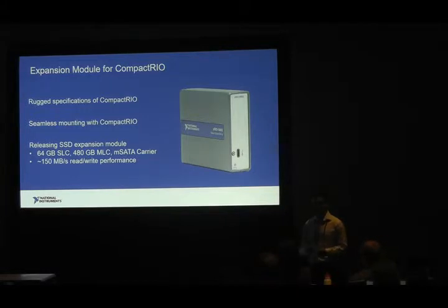For the CompactDAQ chassis, you need some type of OS in the way to do the file management and data storage. But the existing CompactDAQ controllers, you could integrate this alongside as well, because it is just a USB port. We are using USB Type-C on here, but you can use a USB-C to A converter to connect to existing USB 2.0 ports. You just won't get the read-write speeds that you do out of USB 3.